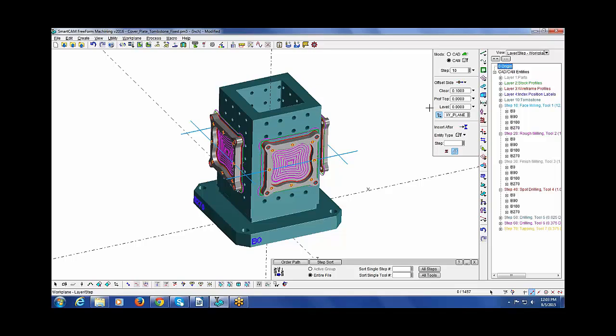We've shown you that you could sort the list by clicking on a heading, so you could sort all the tools in diameter order, ascending order. And we've shown you that you can now load single items from the library or multiple items. To summarize the model view functionality, it allows you to easily distinguish what you have in your model and how you have your model organized.